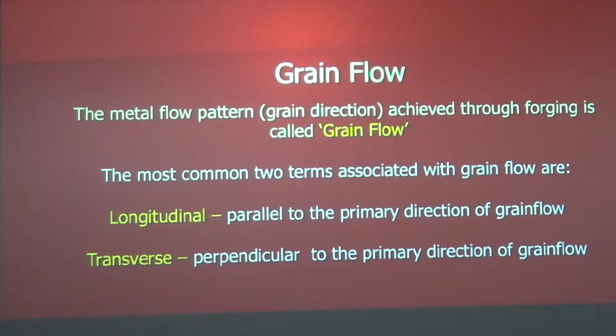This is kind of like your microstructures, if you've taken the class that deals with microstructure polishing, a transverse versus a longitudinal section through something. We can use metallography to establish what direction something has been processed in by looking at the grains, in particular looking at the micro inclusions and seeing how they've been stretched out. That allows us to backtrack. If we don't know, we can go find out how it was processed. Okay, so moving on.